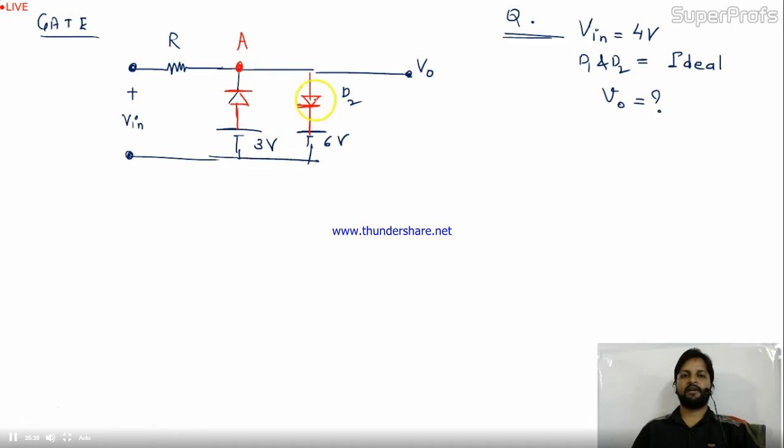If they are open, the voltage at VA is 4 volt or not. If they are open, VIN will be here only 4 volt. Now if this branch is throughout the 4 volt branch, connect this D1 first. What will happen, we'll check. If you connect D1 with 4 volt at the negative terminal and 3 volt at the positive terminal, D1 will not work in the circuit.